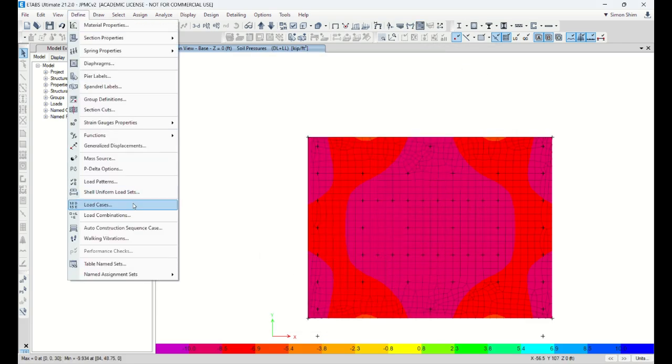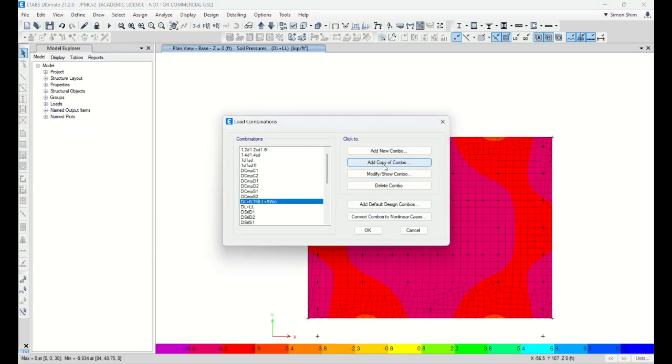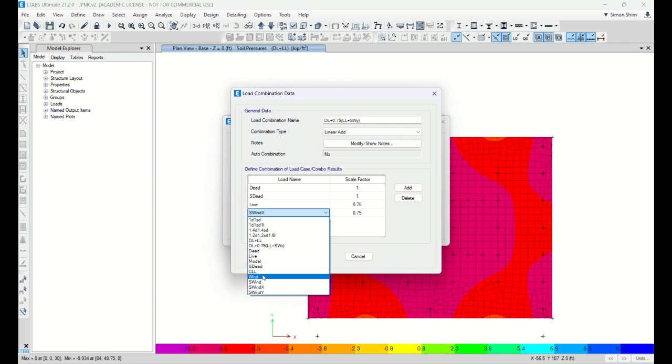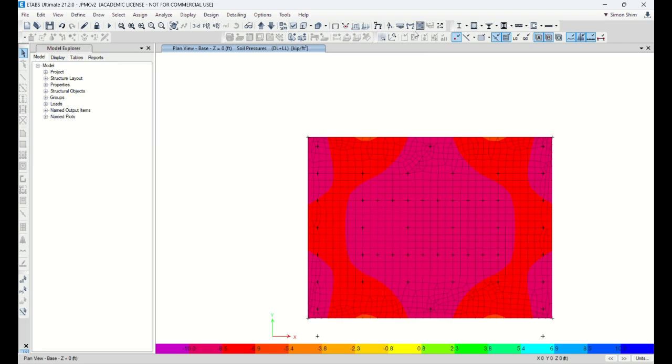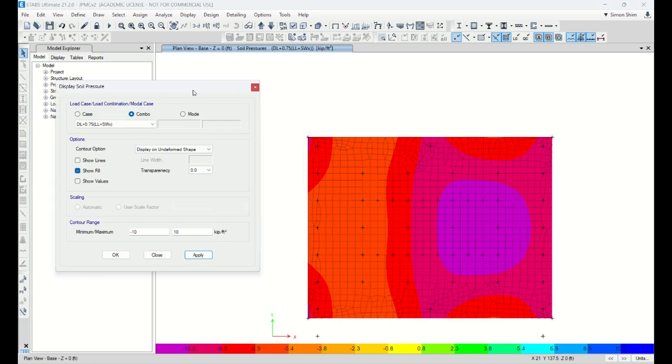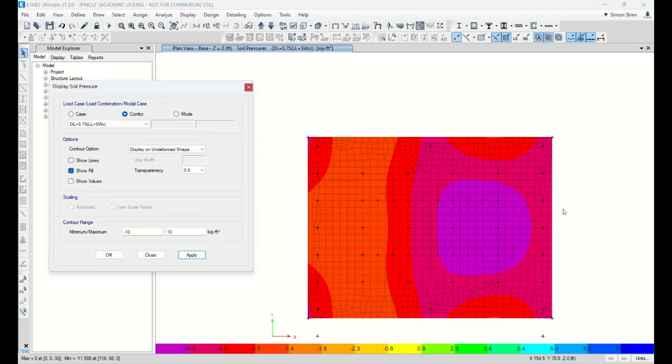All right, so you could also create the load combinations for X and Y. In this case I'm gonna create the Y direction and change to service wind load Y, right? So I'm gonna also check the wind, the gravity effect in combination with the live load and wind X. So wind is blowing to the positive X, which is creating overturning effect.